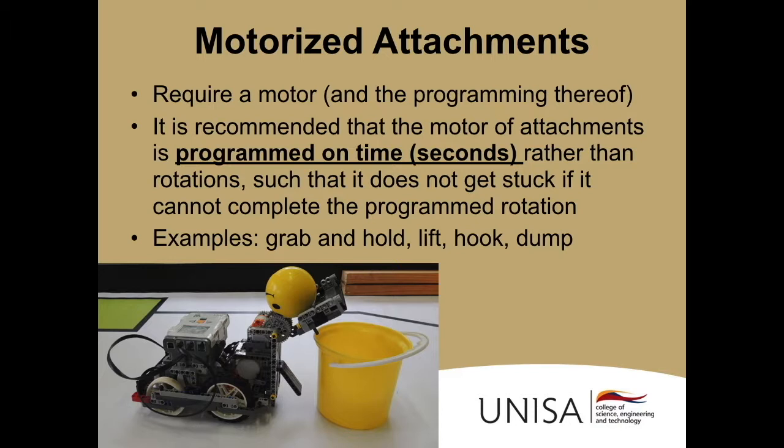And when we programmed motors previously to move the robot, we mainly used rotations to program the motors, because then the distance traveled didn't depend on the power of the motor or the speed of the robot. Here with motorized attachments, it's recommended that you program the motor using time as a mode instead of rotations.